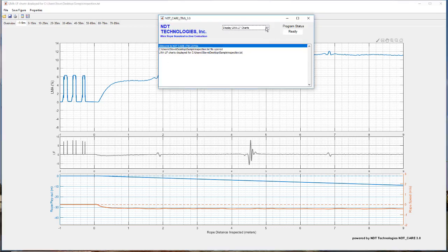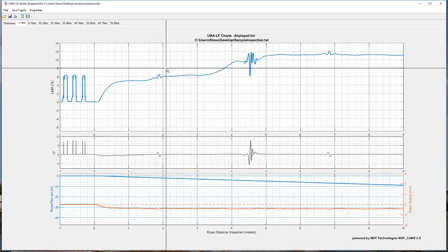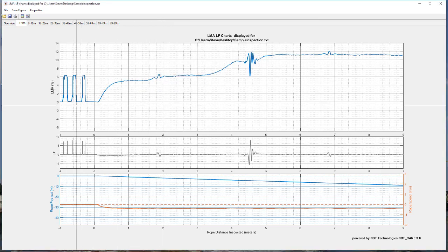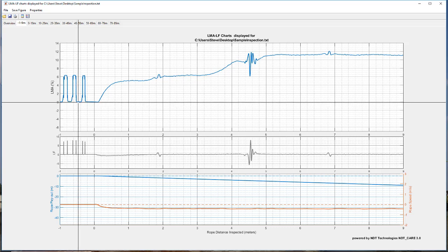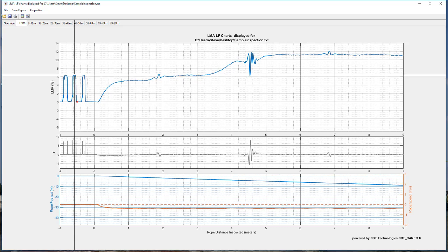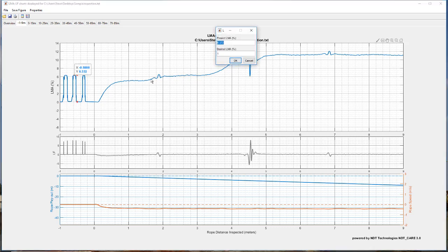So now that I have that zoom, I'll go here and I'll do post calibrate. Once I do that, a set of crosshairs appear, and I'm going to select 2 points. First, roughly the low point on where the calibration is, and I'll say somewhere about there, and then a representative high point, so I'll say maybe right about there. Now what that does is it shows me the distance between those 2 points, and it's highlighted here. It's roughly 6.372, and maybe we want to make it just 6%. So that's something you can adjust based on what you want those calibration wires or rods to mean in your analysis. So I'll say 6%.